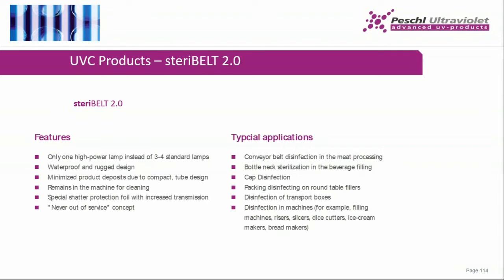But there is something that's really important. If we talk about the disinfection of a conveyor, we have a process where we go and go again with the radiation. So that means a multiplicated effect. If we talk about packing material disinfection, we have to take care that the dosage is just in time, short before filling. Let me make an example. If you have a yogurt cap and you use a UV light, you have to take care that short before filling, you have the right dosage. If you use a conveyor and it passes the lamp time by time, we have an additive process.